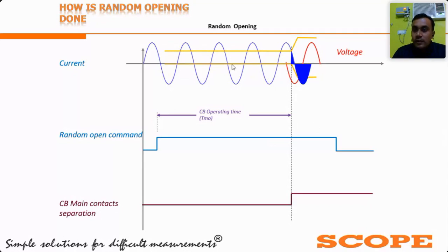This effect is the next half cycle of the current. It is showing here the reignition or re-striking inside the breaker contact. Due to this, there are great bad effects in between the contacts, and this may also arise problems in our equipment's windings or reactor windings insulation.